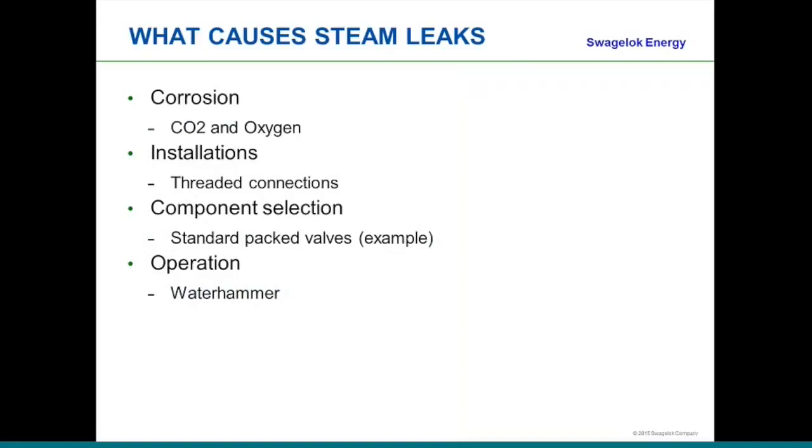On root cause analysis and any correction, part of your change is a very aggressive root cause analysis program to understand what caused failure. So doing root cause analysis, you will find that CO2 corrosion, sometimes there, but oxygen corrosion probably is going to be a more dominant player in causing steam leakage. So you must look at oxygen corrosion.